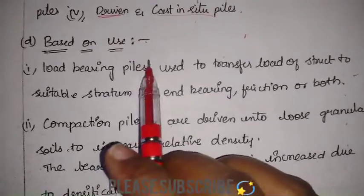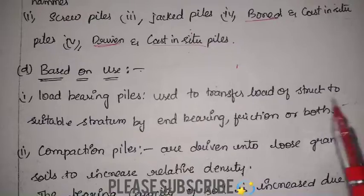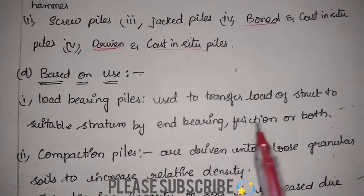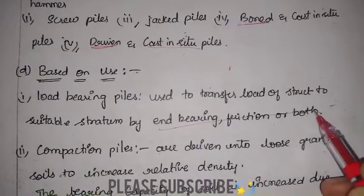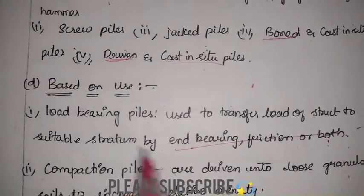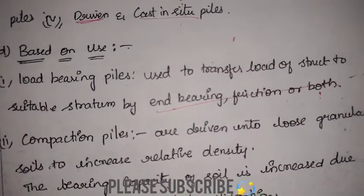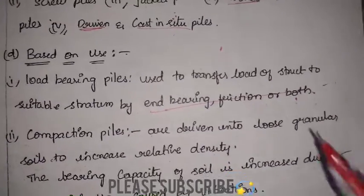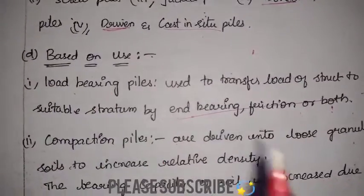Next, based on use, we have load bearing piles. These are used to transfer the load of the structure to a suitable stratum by end bearing or friction or both. Here, instead of the mechanism of load transfer, we are seeing the use, that is, with what requirement you are going for this pile foundation. If you need the load transfer mechanism, then we call them load bearing piles.